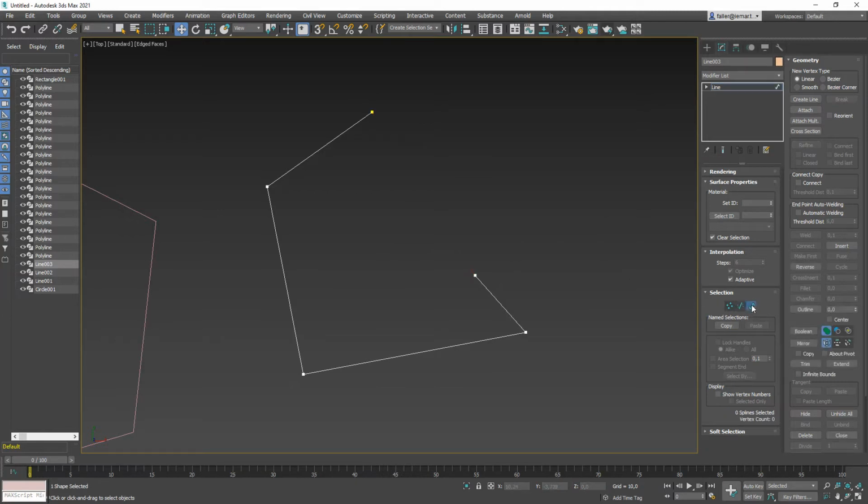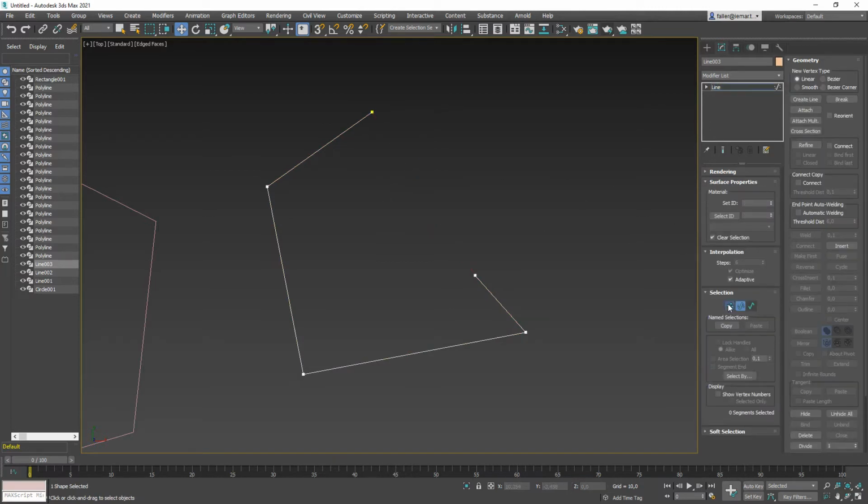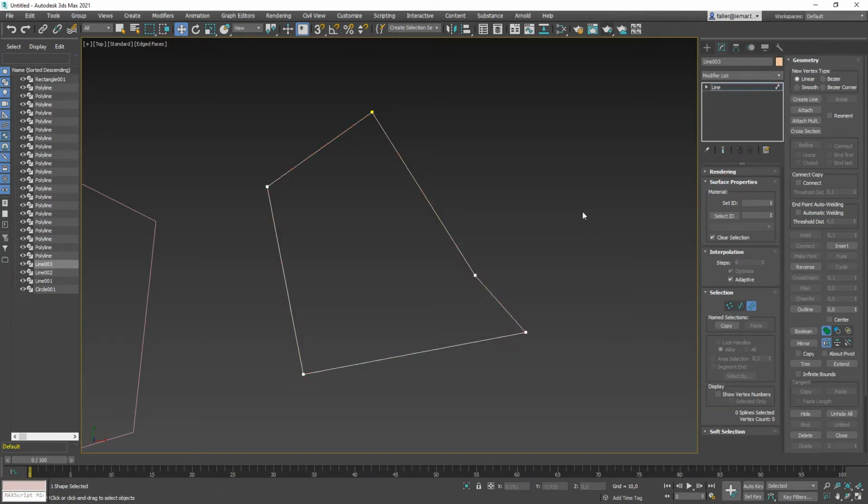And now you go into spline level, check again, of course now it's open because you see there's a big gap, and now you hit close. And now what it does, it creates a new last segment and closes it. So hit close, and there it is, it creates a new segment. You could also do the same thing that I've shown you in our last video, and that is, let me do it again. Delete this one segment, go into vertex level and choose connect. With connect you can click and drag onto here. It creates automatically the last section and will weld it together, and now if you check it you'll see it's closed. Okay, so that is closing it manually.